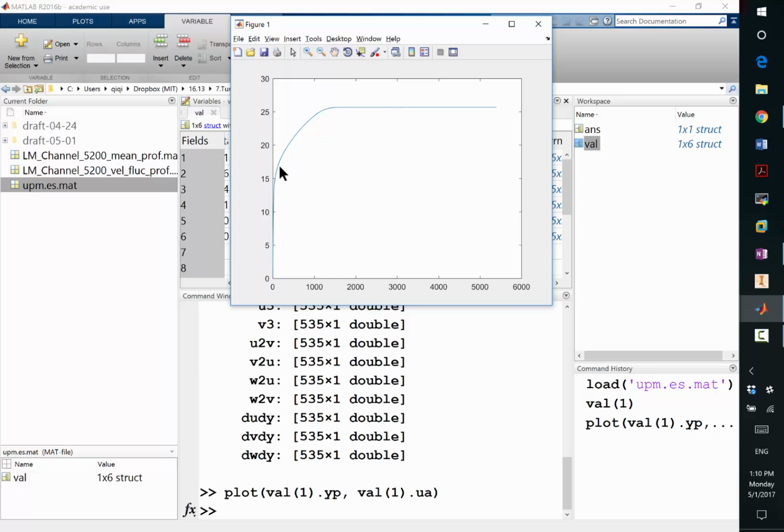So that shows a characteristic of a turbulent boundary layer. You have very sharp velocity gradient near the wall, and on the outer side of the boundary layer, the velocity gradient is much shallower, right? That's very different. You can just see clearly that is different from a laminar boundary layer. All right. And to see the profile more clearly, we want to plot which axis in log scale?